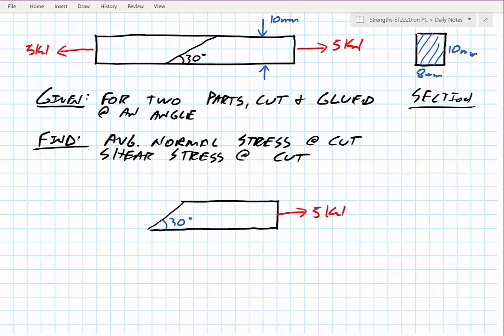There's two forces. One is your axial force, your average normal, which is perpendicular to the surface, and we said last time we're calling it P. And then I also have a shearing force, which we're designating now as V. Now, those two forces would be perpendicular to each other because one is perpendicular to the surface, the other one's parallel to the surface, so by nature they have to be perpendicular.